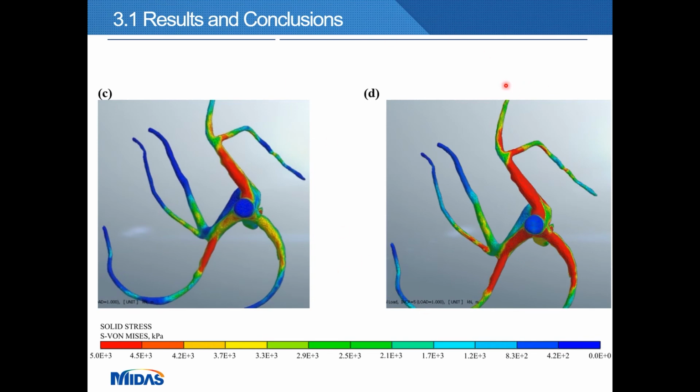We will see that there is a concentration of stress in the tree. As I pointed out before, the stresses are higher if the stiffness of the soil is higher. So if we are experiencing higher matric suction conditions, the effect of the structural roots will be higher in terms of wind resistance, tree stability and tree failure. So when we experience higher matric suction conditions, we will have higher stresses on the roots.